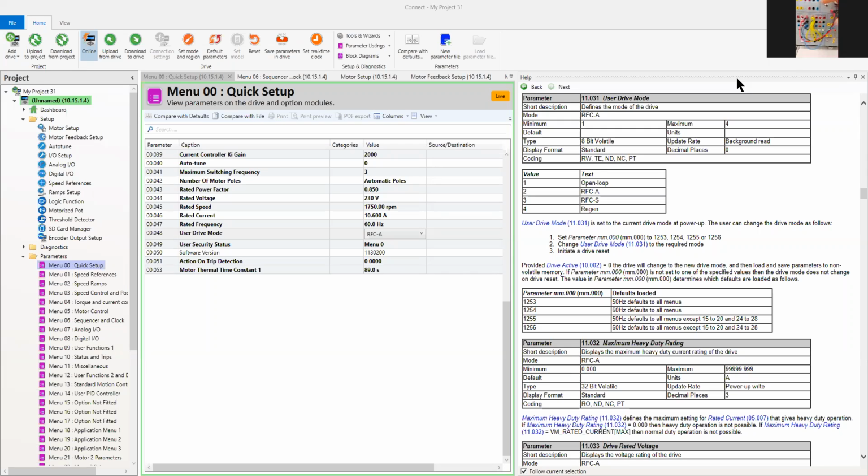as feedback for my induction motor, which is an asynchronous motor. We already have the wires connected to that motor. We need to apply the information for this motor, information for that feedback, go for tuning, for auto tuning for this one, and then for the loop, two forms of PID control tuning, and then acceleration, deceleration.